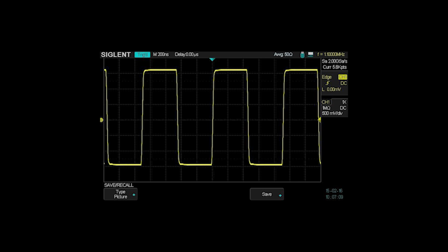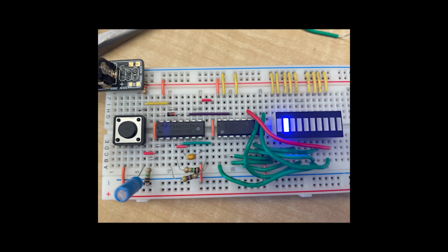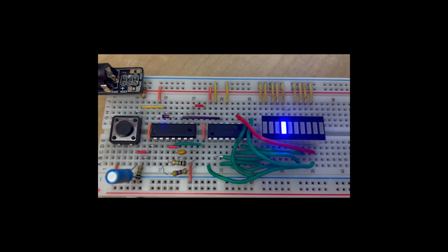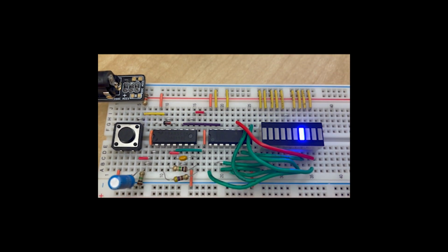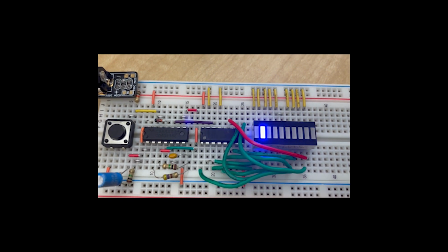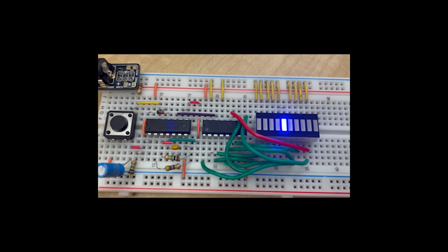Moving on to our next stage, we have the decade counter. This component serves as a pulse counter, recording the number of clock pulses from the NAND gate oscillator. It's crucial here to ensure all input pins are properly conditioned. Conditioning involves making sure each pin represents a valid binary digit, either 0 or 1, to guarantee accurate counting.